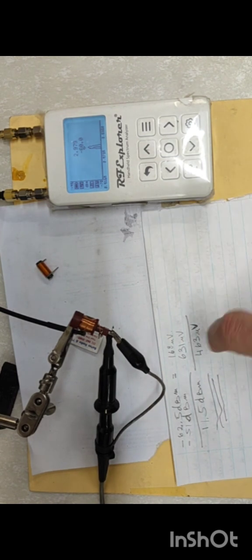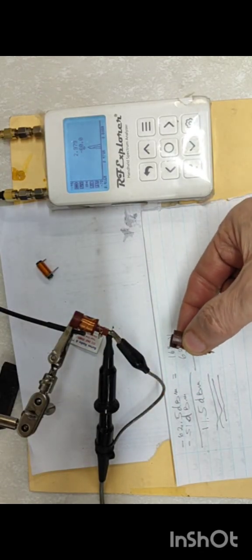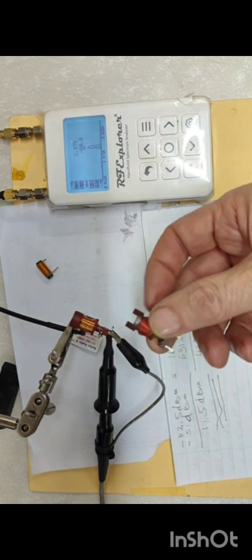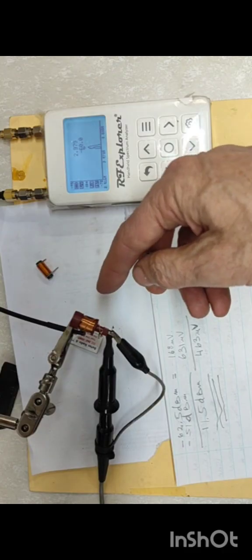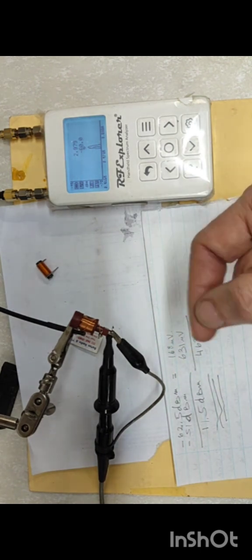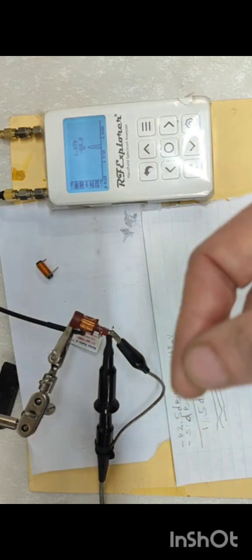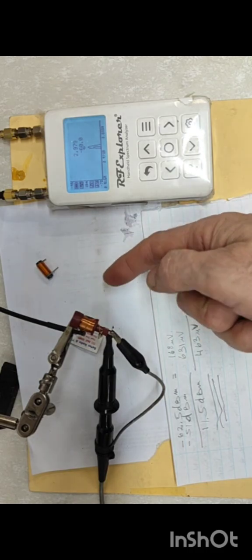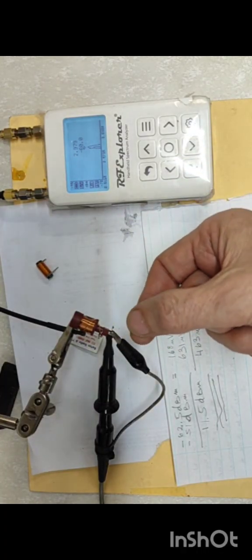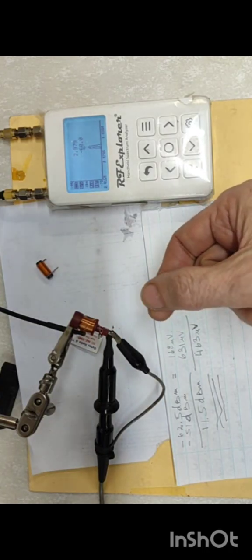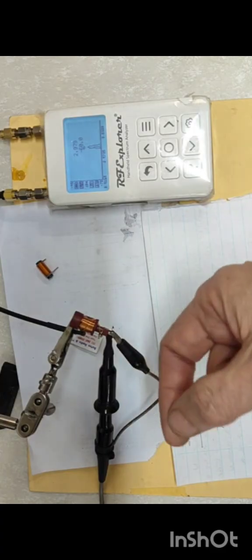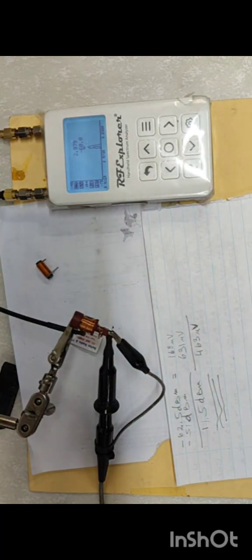And the difference in how you put the inductor can reduce harmful emissions from that coil in the electronic circuit where you're going to use it, by up to 15 dB. And 15 dB means approximately 50 times lower emissions, interference and noise generated from this coil. Why is it significant? Because it will make a big difference between bad, failing, or good, passing limits for EMI, that's electromagnetic interference, and for the operation of the switch mode power supply. So it is very, very essential.